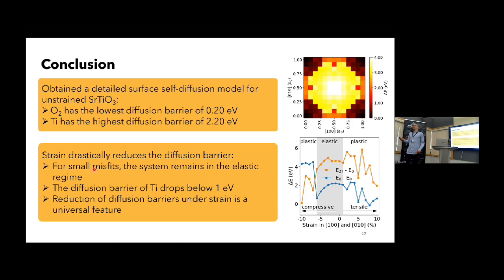I mean, yes, you're correct. For very large plastic deformation to see the effects, we need a much larger model. But our data of the atomic coordinates shows that at some points the atomic coordinates don't follow a linear curve anymore. So if we strain the system by 1%, we should see each atomic coordinate move 1%. But at some point, at some stress, we see it's not linear anymore, but it starts jumping. So some atoms move much more than others. So you do see this disintegration of the original. Yes.